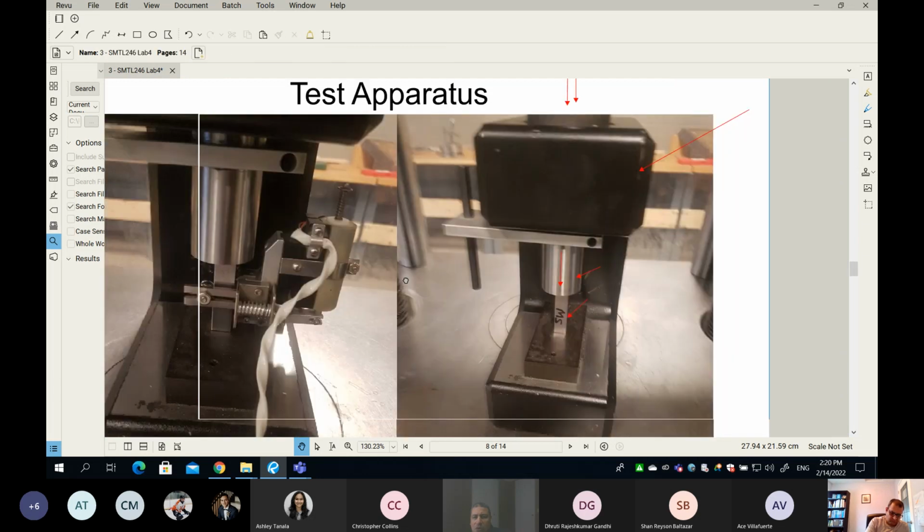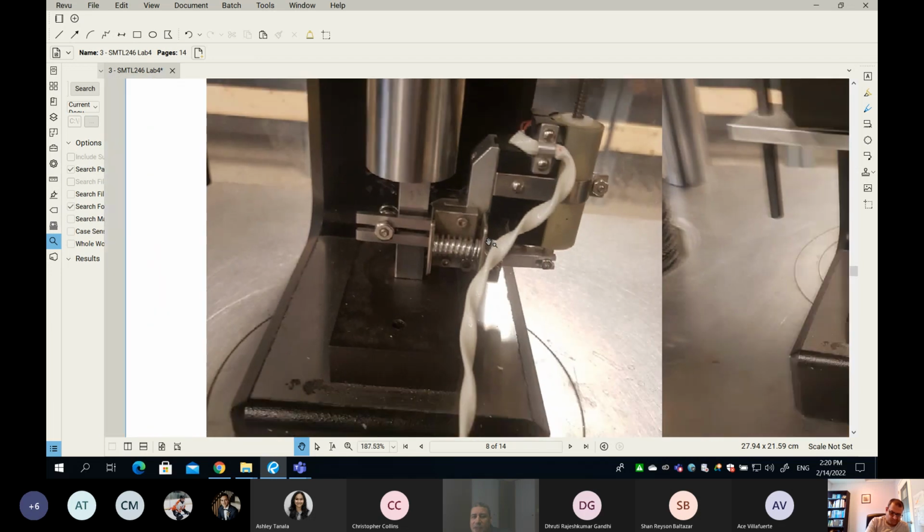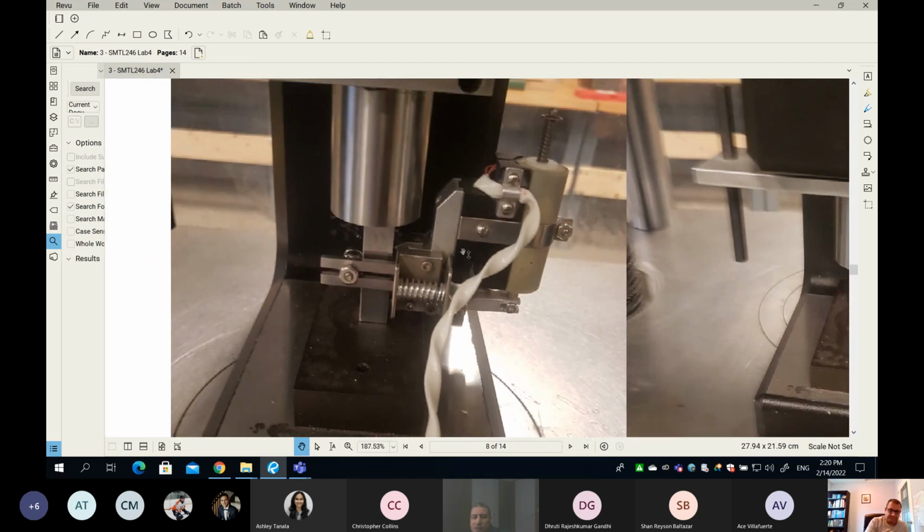All right, remember also that we're not only measuring stress, but also we're measuring strain. So how can we measure strain? Anyone to help? How do we measure strain? The strain is the change over original length. Yeah, but how can we measure it? How do we measure it? You can see this device. So this device, anybody still remember the name? What is the name of this device? It's called an extensometer. Extensometer, yeah.